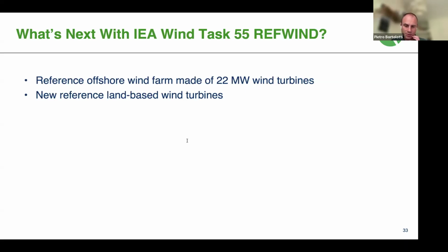Frederick, one question for you on the leading edge protection. Was a leading edge protection system included? No, there isn't. This could of course have some impact on mostly the aerodynamic properties of the airfoils, but it was not considered. Except that, with a 105 meter per second tip speed, we are certainly expecting advancement in leading edge protection systems compared to what's currently done in the market. So definitely you could say on the challenging side of things.